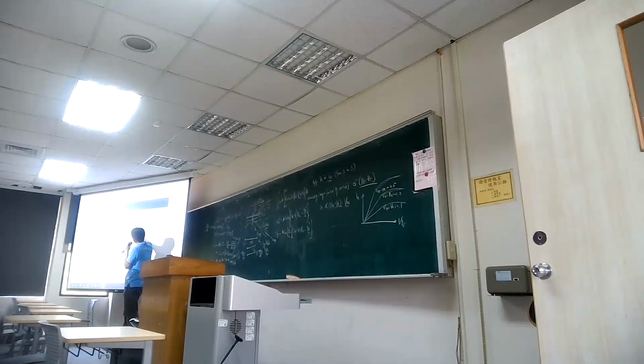Once you place VGS minus VT into the term, the highest voltage available is VGS minus VT. So putting it in for VDS, you get a simple ID equals 1/2 times W over L times mu Cox times (VGS minus VT) squared. You can think that once VGS is fixed, that determines how much channel, how many carriers, we can attract along the surface of the semiconductor. It is the upper limit of your drain current, no matter how much drain voltage we further push up.